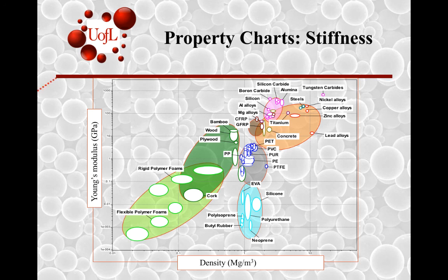We saw how to get a selection line of a suitable slope that depends upon the loading condition and the material index thereof, and allows us to filter off options and down select certain options that satisfy design criteria.